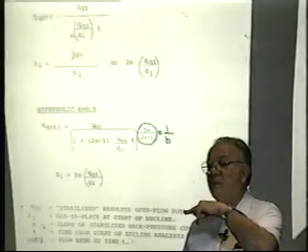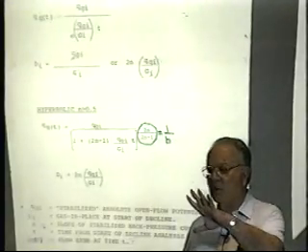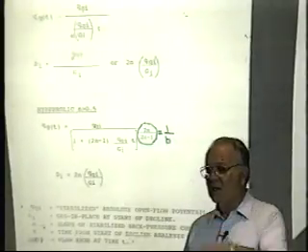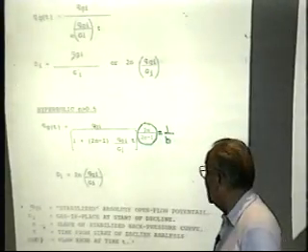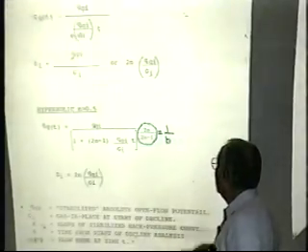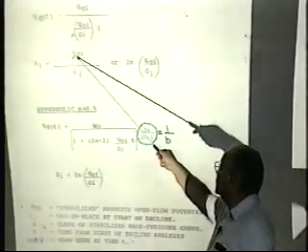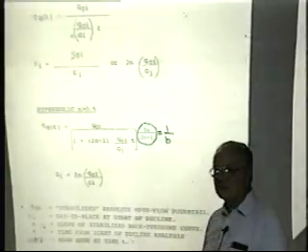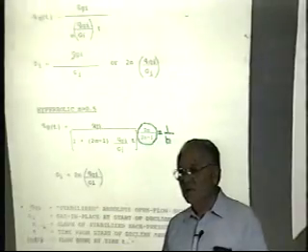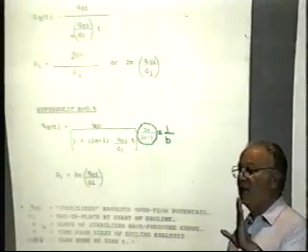We'll work out an example later where we'll show you how to treat it if the flowing pressure isn't zero. But don't worry about it. Again, this is how you end up with the equations. Very simple equations when you're going to assume the flowing pressure is essentially zero. And for exponential, D sub I is equal to the absolute open flow over the gas in place. That's the initial decline. It's got a physical meaning, and you can calculate that.